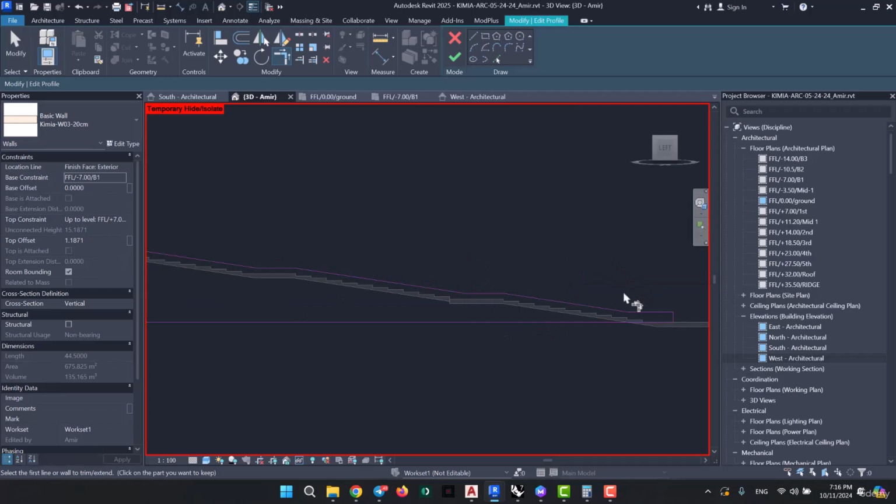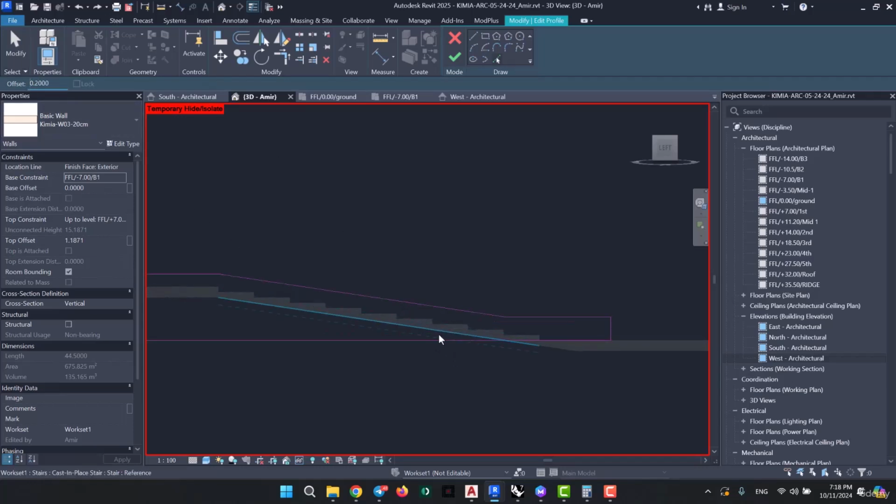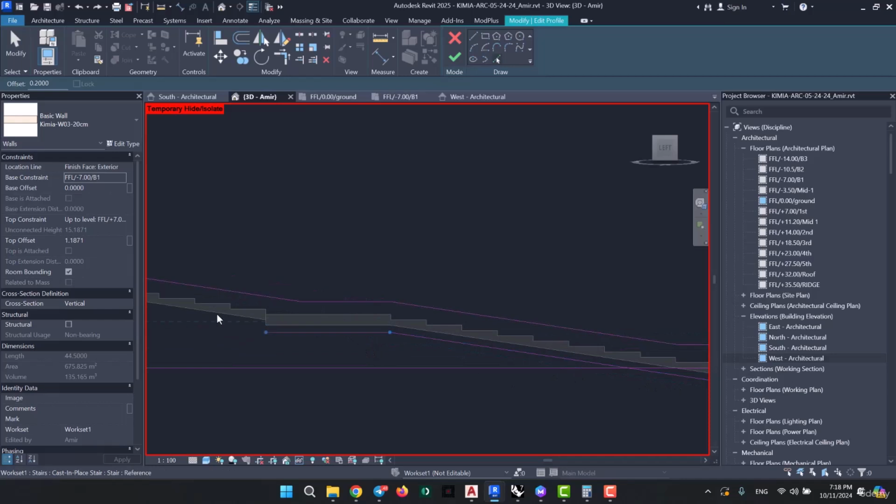of the stairs. So now that I've trimmed all the lines, the bottom side below the stairs really just depends on the details as to whether it should be filled or if there should be a belt below the stairs aligned with the slopes. But because we have topography in this plan, the wall shouldn't be going all the way down like this. So it might be better if we had another offset lower than the stairs. For example, I'm going to make that about 20 centimeters, then place another offset here underneath this entire stair path, like so. Now let's add the others.